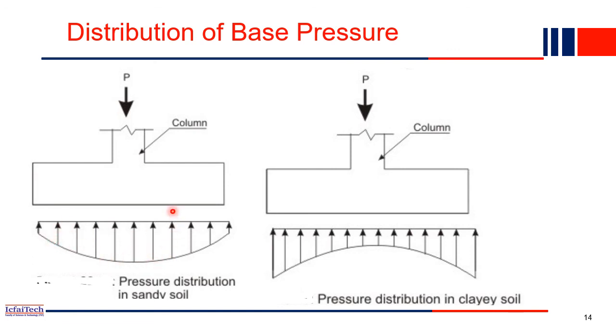At the center of the footing you will have maximum pressure, whereas near the edges, pressures are reducing. Whereas if the soil is clay soil, then the pressure will come something like that. Depending on how much pressure is coming, we have to design the reinforcements here. For one type of load distribution we design one type of foundation, and for another type of distribution we design another. So depending on the distribution of pressure, we have to design.